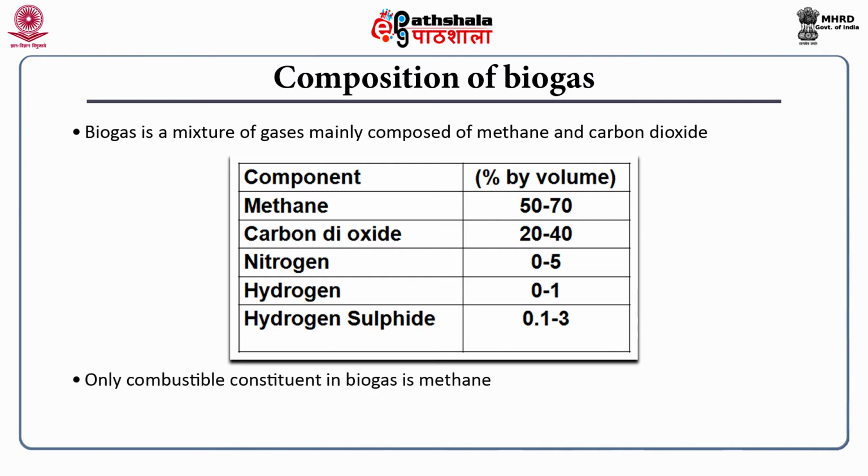Methane is the chief combustible component and it determines the biofuel property or quality. The relative percentages, the quantity and quality of the gas produced during anaerobic digestion depend on the quality of the feed material and the process conditions we use for this production. Normally, it is rich in methane with major impurities of hydrogen sulfide, carbon dioxide and water, and it has a calorific value of 5000 to 7000 kilocalories per cubic meter.